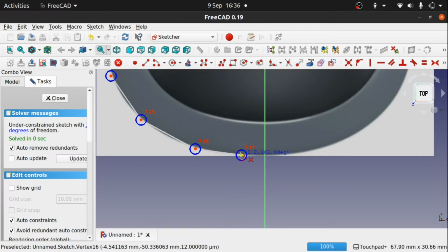When we get towards the bottom, we need to connect up with this vertical axis again. And it's best to try to keep this straight on from the last point. So this point here, you can see we're more straight onto there. That makes a better curve when we come to bring in this around here on the mirror. So I'm going to hit escape to get my mouse pointer, and I'm just going to coax these into position by just moving the handlers here.